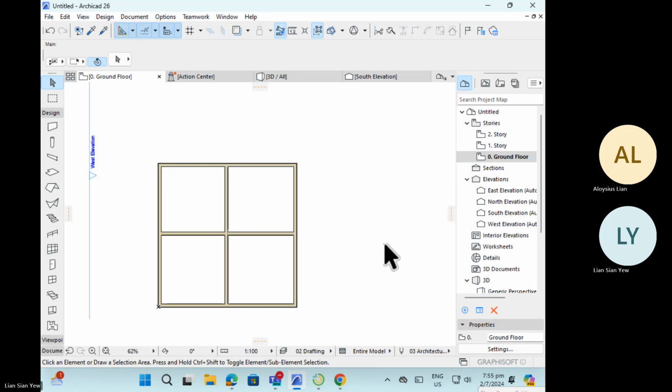Okay, so now what we want you to do is to be able to trim the wall. Okay, so that's available here on the top. Look at my giant arrow. You should be able to see it's next to the hammer. It's a scissors icon. So you click on it here, and then you can trim. Click again, trim. Click again, trim. Click again and trim.